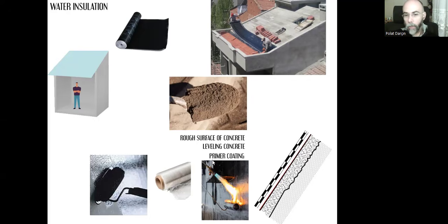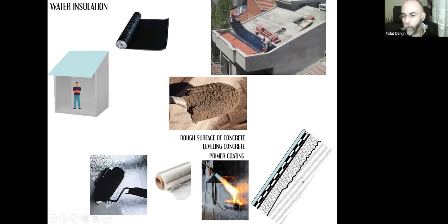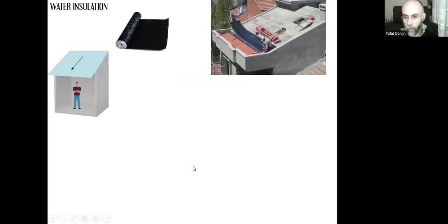That's why we first use primer coating. And once we do the water insulation, we can proceed for either heat insulation or the finishes over this water insulation.